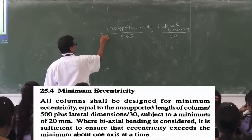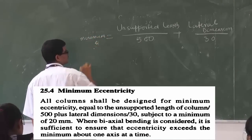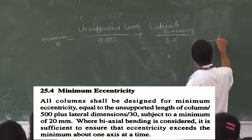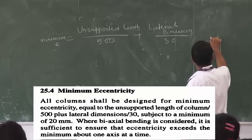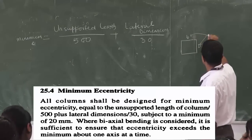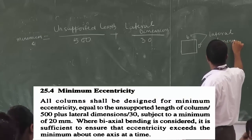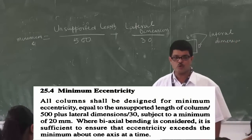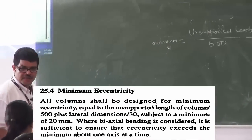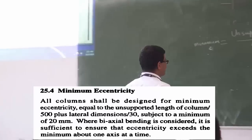So this is the minimum eccentricity. You have to calculate the minimum E value. Unsupported length means, suppose you are taking a column that has two dimensions. One is the B value, one is the D value. B and D are called the lateral dimensions. So the length of the column you know, then unsupported length by 500 plus lateral dimension by 30. That you have to find out, subject to a minimum of 20 millimeter.